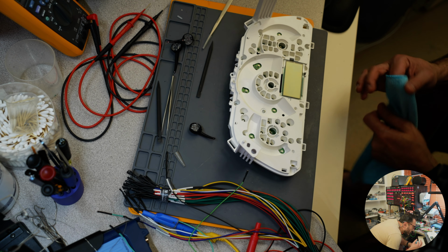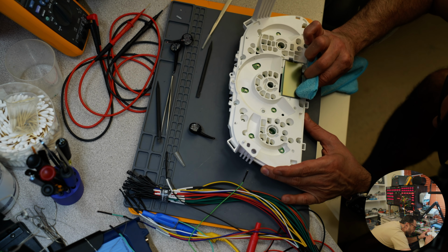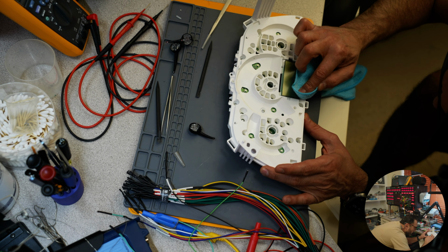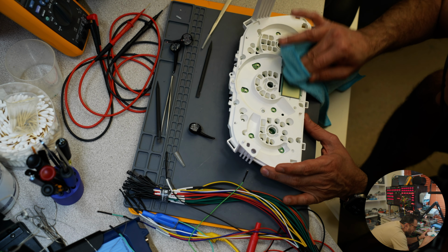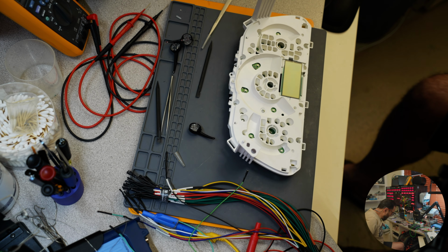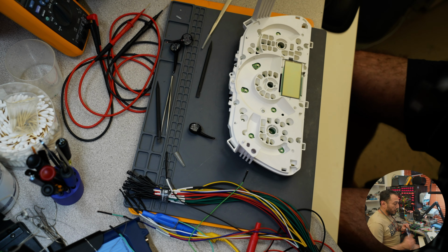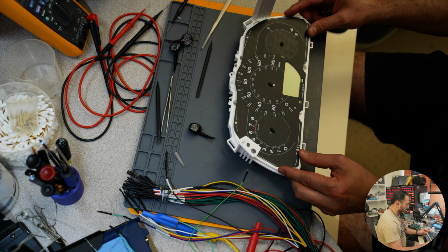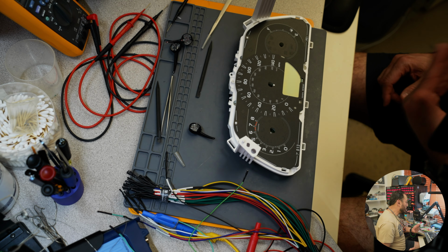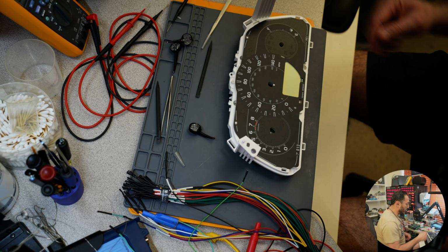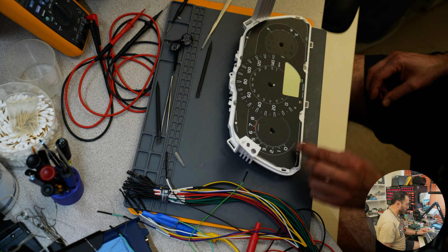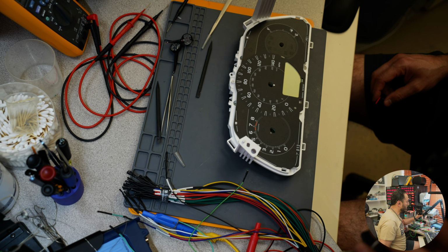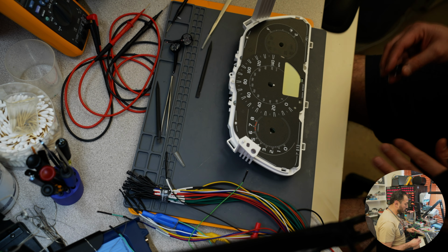It needs to be pushed a little more this side. Okay, that's looking good. Another way that you will find out if it's not all the way in is when you're trying to put the face. The face has a position on the center that will be pushed up if you don't do it properly. The needles, I always put a small mark onto with a white marker so I can find out where to install them back. But I always also take pictures to make sure they're in the correct position.